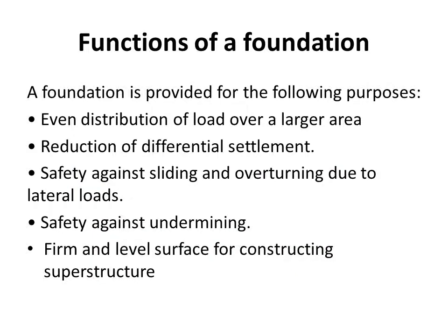Functions of a foundation. A foundation is provided for the following purposes. That is, even distribution of load over a large area, reduction of differential settlement, safety against sliding and overturning due to lateral loads, safety against undermining, and a firm and level surface for constructing the superstructure.